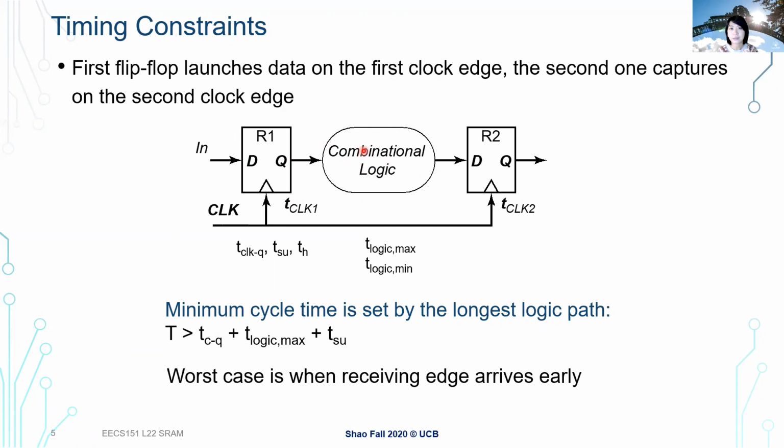We did a quick exercise last time. When you think about combinational delay, one very important thing is also to recognize what false paths exist in your combinational circuit, not just doing the max of all the possible paths. Sometimes the paths are conflicting with each other. So you also need to analyze your circuit carefully there.